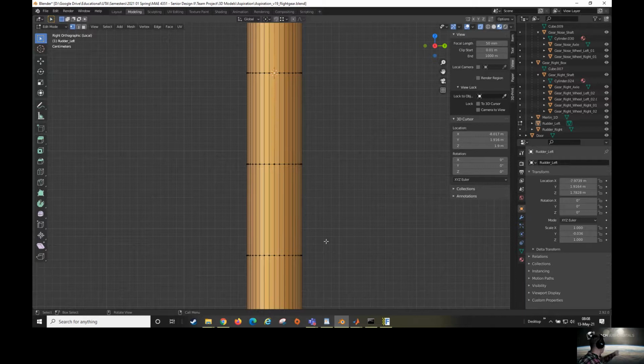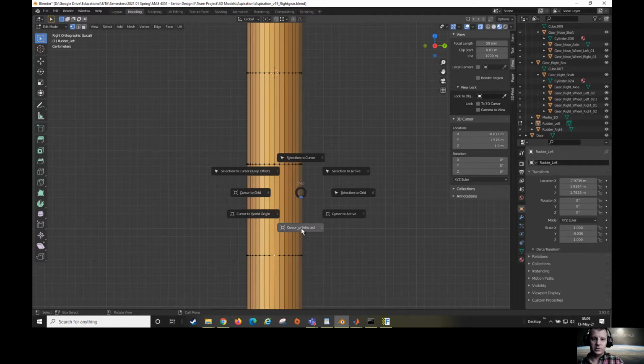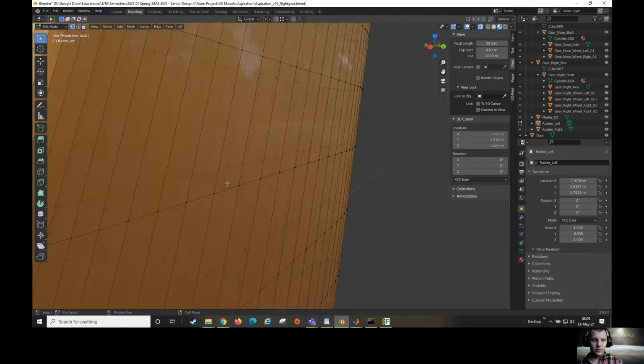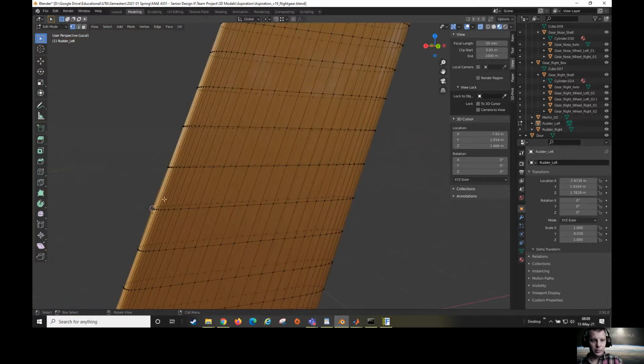I wrote down on the board all of the positions for a whole bunch of nodes, or in this case vertices. And so here I wrote down the XYZ, and then I took the point opposite of the center origin, and I wrote down these values. So what that's going to do is provide 2 points on this axis. That's going to cause the rudder, in this case, to pivot around it.